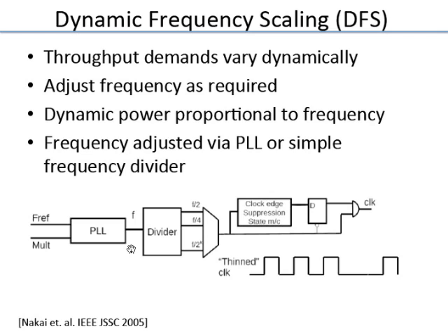Instead, a simple way of changing the clock frequency is to use dividers. Say you generate a 4 gigahertz clock, and your chip requires 2 gigahertz maximum. You cannot go beyond 2 gigahertz. You have a 4 gigahertz clock coming in, which you divide by 2 to get 2 gigahertz. If I want 1 gigahertz, I put in another divide, and so on. I don't do anything to the PLL. Everything is done digitally outside. So that is what these guys do.